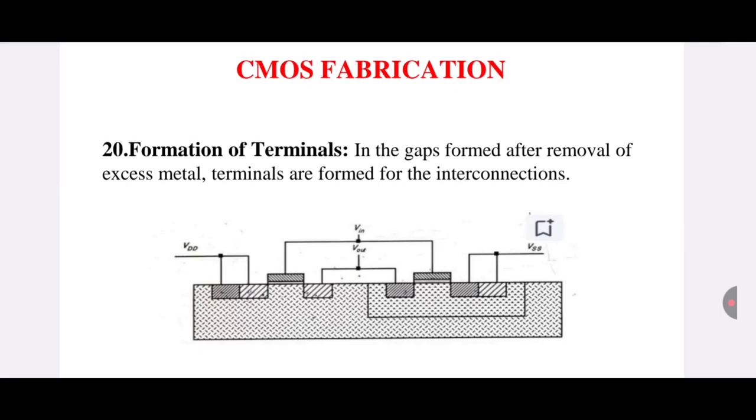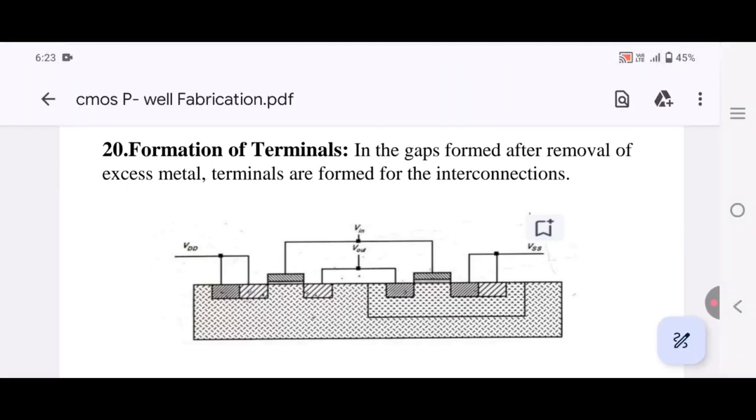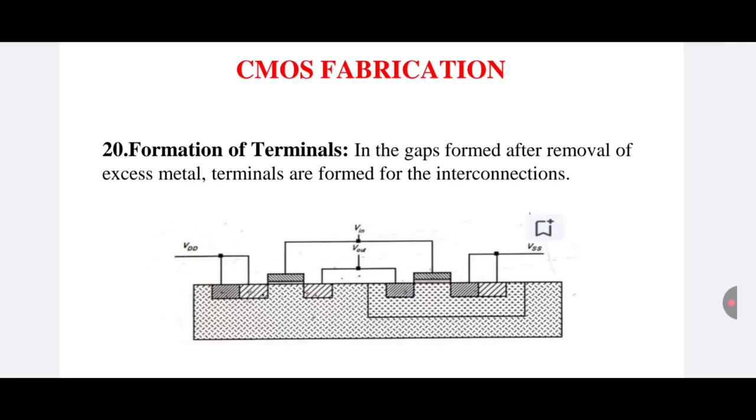Here you could see all the gate terminals are connected together in order to provide the input, and one of the source and drain terminals are connected together in order to get the output out of the device. So thank you so much.